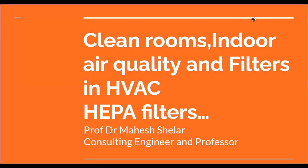One is known as the coarse filters. Coarse meaning the sizes of the particles which are being trapped by these filters are bigger in size. So the filters that are efficient in trapping the coarse dust particles are known as the coarse filters. Then come medium efficiency filters, which also trap sizable particles, that is fine dust particles, but their sizes would be below the coarse filter sizes.